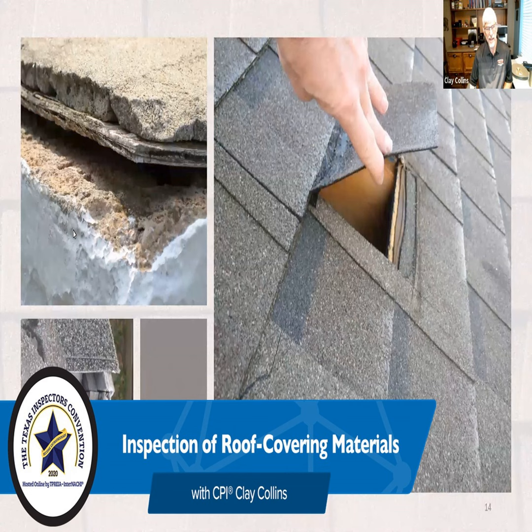I do report it if it's loose. So what can cause damage? We talked about some of that, but here's another case of the installer laying the shingle on top of it and cutting it. Did that go through enough to damage the shingle, and is it going to leak? I don't think that's going to leak, but it is poor workmanship.